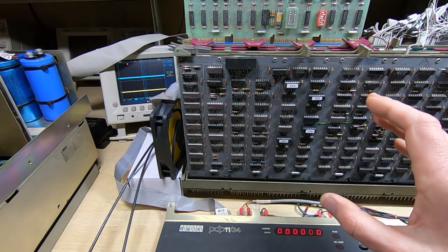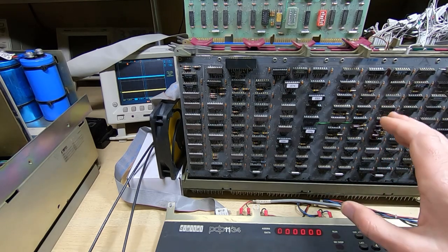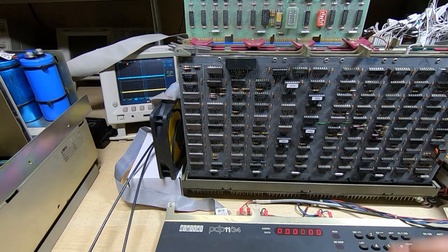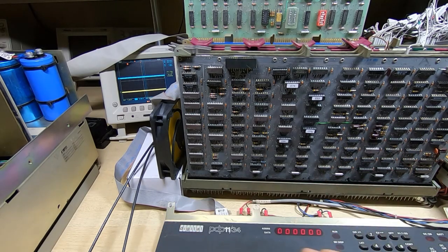The problem when you get a fault like this is where to start looking, because it could be a fault with the main PDP CPU, it could be a fault with the interface, it could be backplane memory, it could be the control card on the floppy disk, the drives themselves, the interface electronics. And so it all gets a bit complex, and on top of that you of course have configuration.